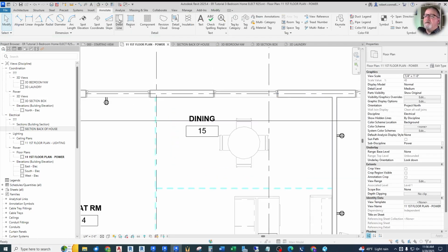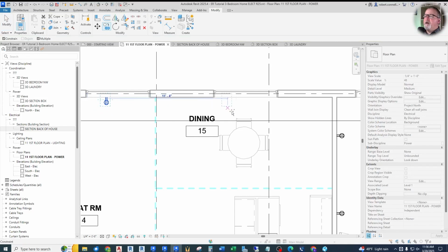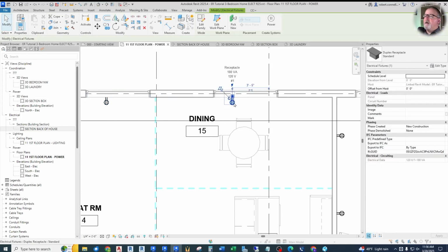And we'll do the same here. Now I could just copy this from here to less than 12 feet there. Now, what happens here is it put it down at 0. So the copy is not always a reliable way to duplicate something. It's messing with its height. So let's get rid of that.